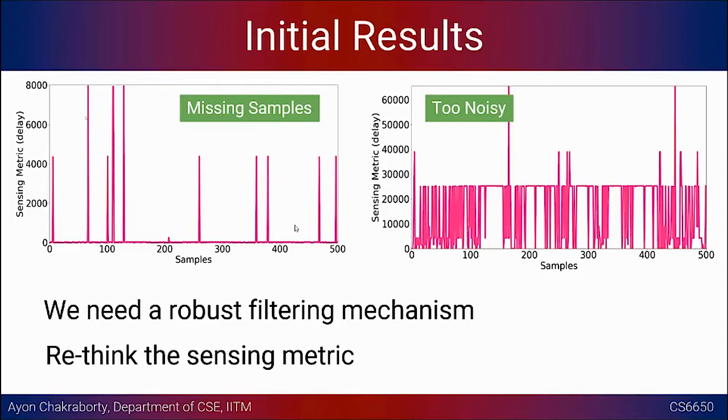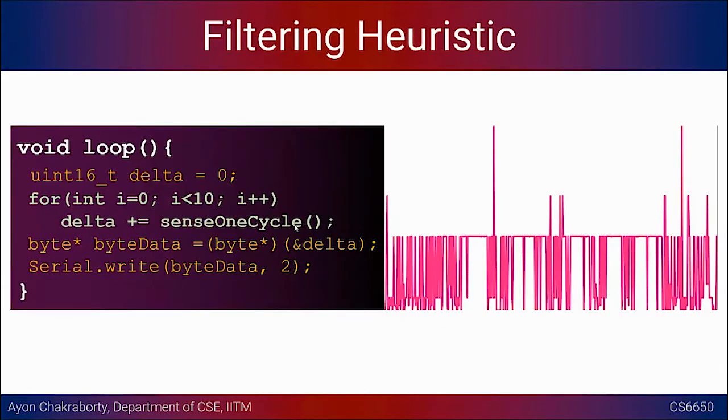That is how a standard event detection is implemented, and here we are detecting a touch event. Just calibrating the delta value will not make much sense, because these values will change from touch to touch, person to person, object to object. We cannot simply base the threshold on that value, so we have to do something better, right?